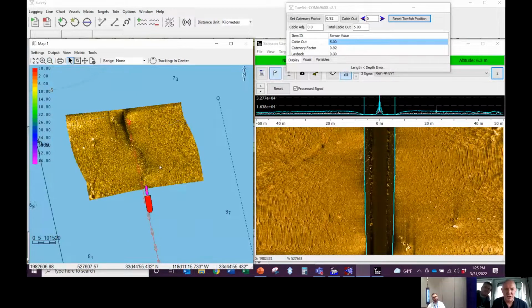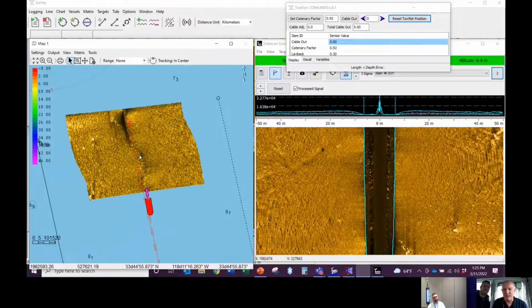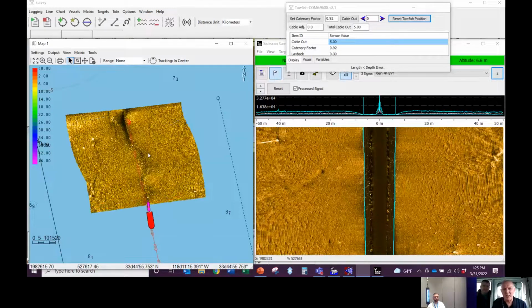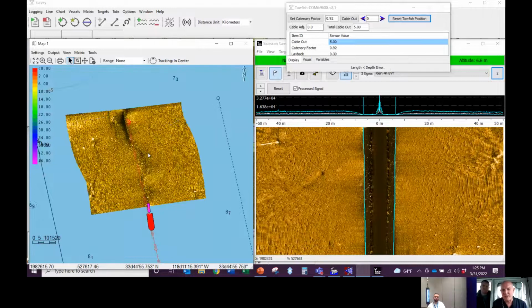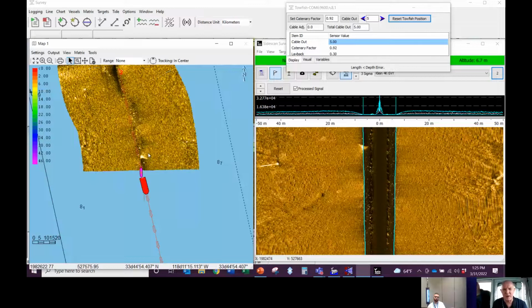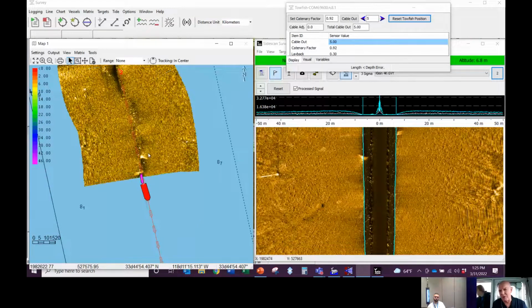So what this is actually doing is HYPACK's generating geotiff images in a set of tiles. And once we close out survey, you can actually plot these up in the shell, or you could copy them onto your flash drive and hand them over to your customer as a preliminary product.